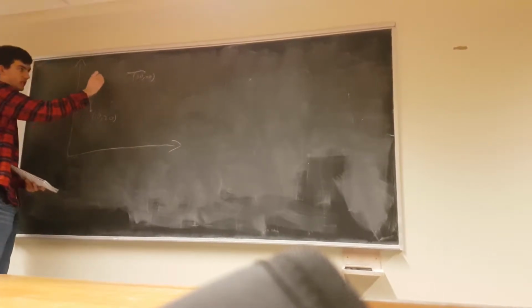That's a non-trivial question. Do we necessarily care what path we take? Most of the time, yes. What if there's a thing here that we can't drive through? A thing there that we can't drive through? What if, in the case of an X drive, sure, it can move in any direction, but it's faster at moving forwards, backwards, left, or right than it is moving on any diagonal? We probably want to take that into consideration if we're trying to do this motion as fast as possible. So that's a question that needs to be in the back of our mind when coming up with a control system to get the robot to do this.